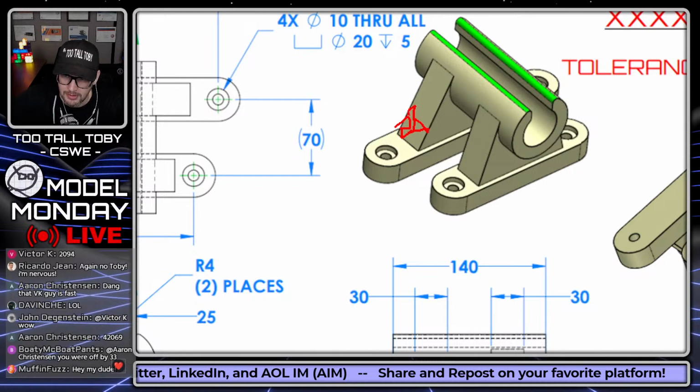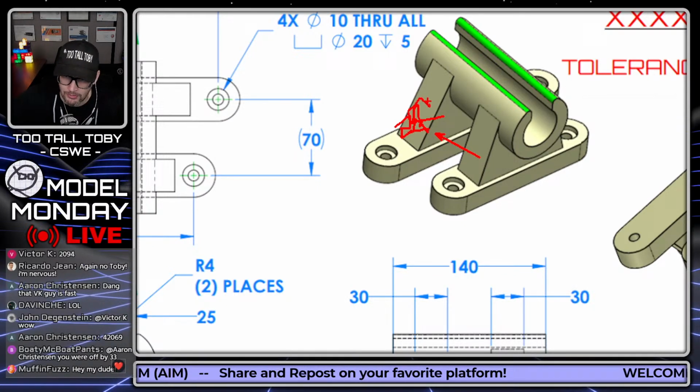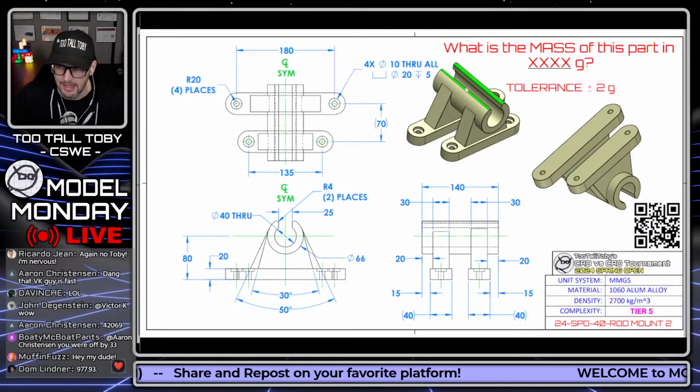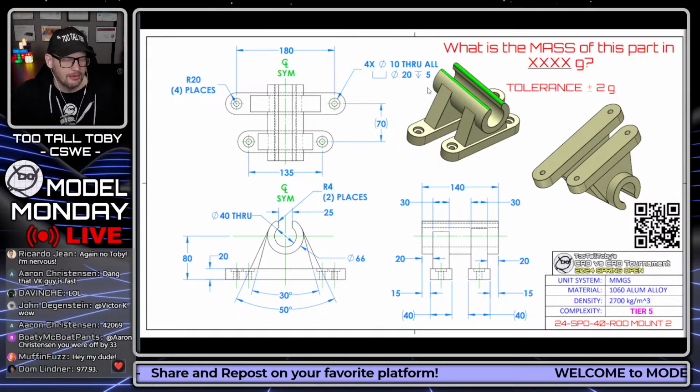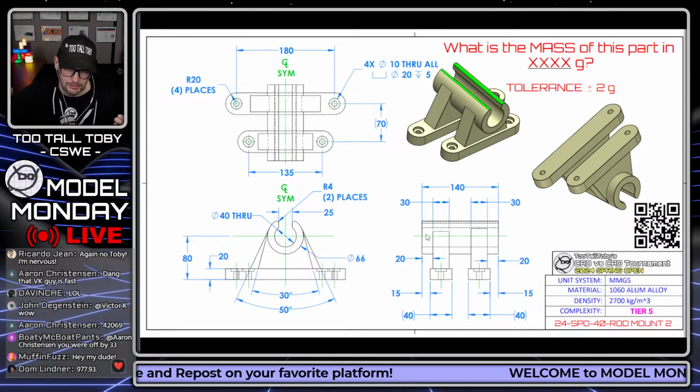And then what you're able to do is apply a force here on this node, and you're able to calculate what that force and pressure is going to be exerted at this mid node and also at this node here. And then you're able to repeat that iteratively throughout all of the elements in the model. And that's called discretizing a model in finite element analysis. Well, in the case of 3D modeling, when I advise my students on how to approach a